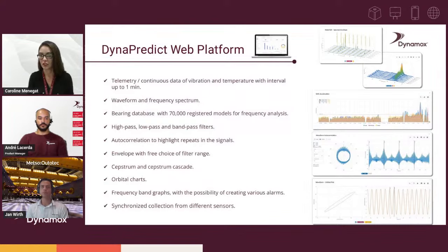And this graph shows why it's important to monitor in three axes. If we were monitoring only one of them, for example, the one in yellow, we probably would take longer to see the problem. As we can see, the blue one is actually evolving a lot faster.